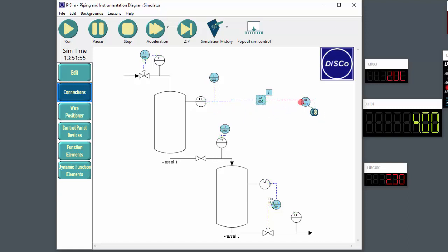Let's connect this thing up. Now what I would expect this thing to do is that we have a nominal steady state value of 2 on this thing. If we're integrating this thing at a 1 second sample rate, we would expect to see this increase pretty much in a straight line because the input value isn't changing. So let's run that just now. Let's put that back into edit mode and we'll run it.